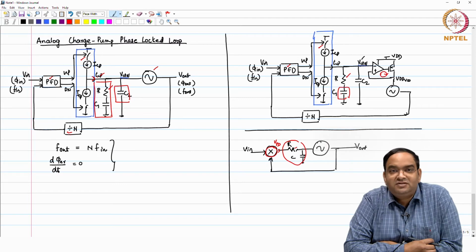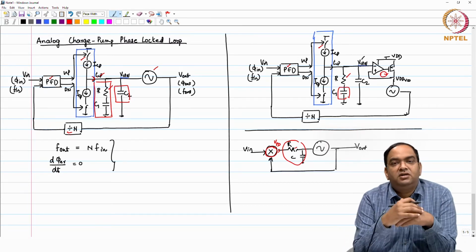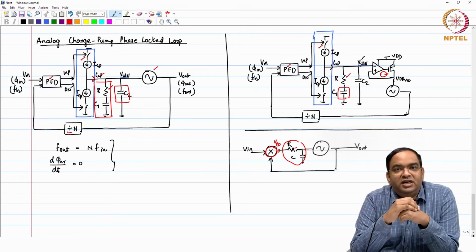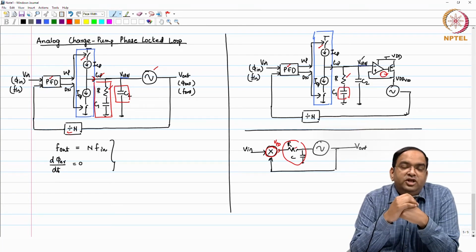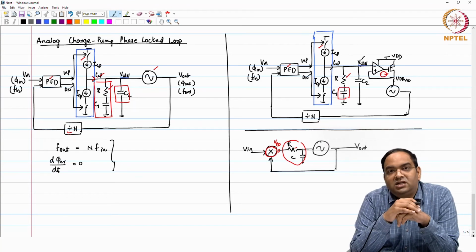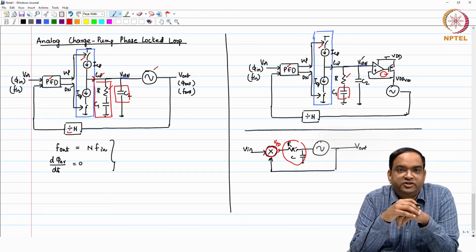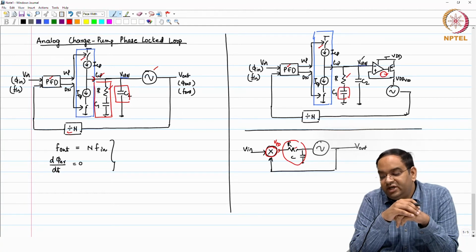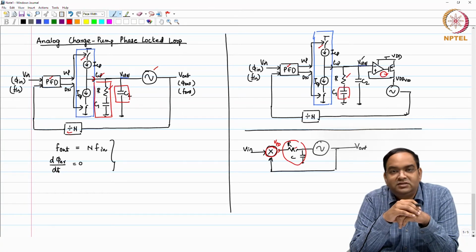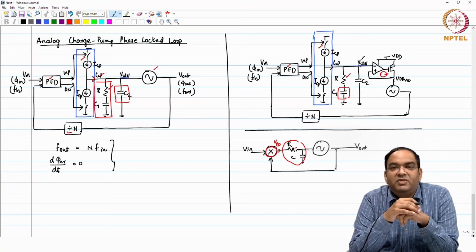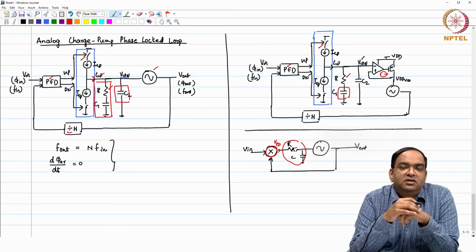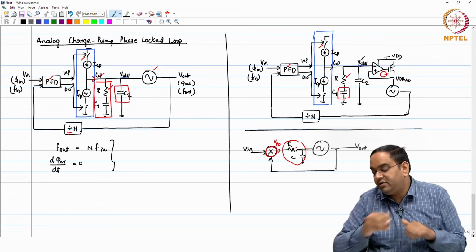So, we replaced this integration which we are doing using a digital accumulator, because we know that as you go down lower the technology, having larger voltages is not possible, and process variations for RC are a lot. Implementing a digital accumulation is much easier. We implemented this with a digital accumulator, right.